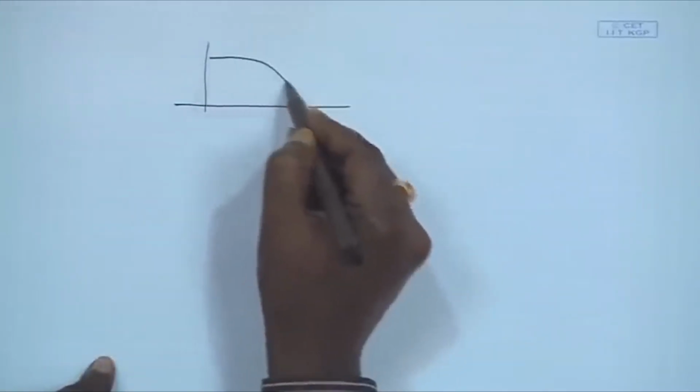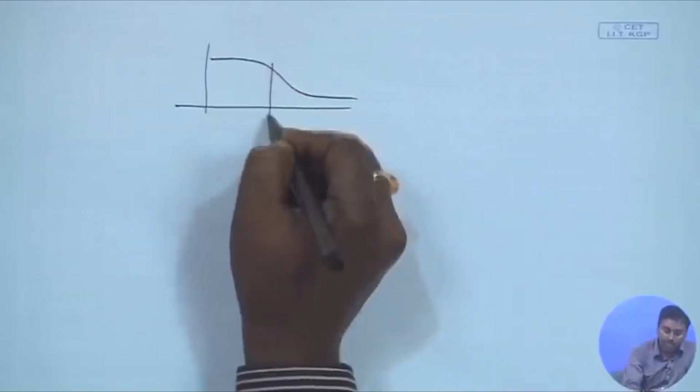So the channel transfer function, if we just see, will almost look like this. Up to some cutoff frequency, it will probably be almost carrying that signal, but after that it will be hugely attenuated. Okay. So if this happens, suppose our signal has multiple different frequency components, then what will happen? Some of the frequency components will be equivalently carried, but some might get a little bit suppressed. What's the effect of that?